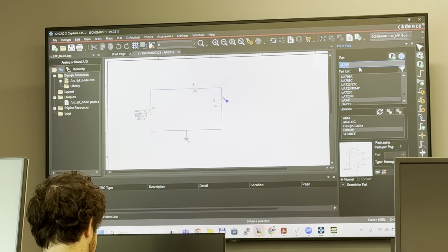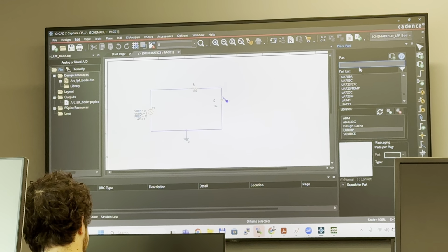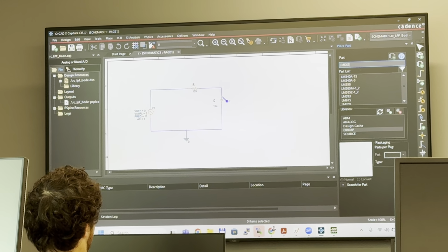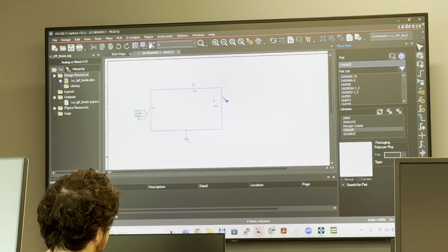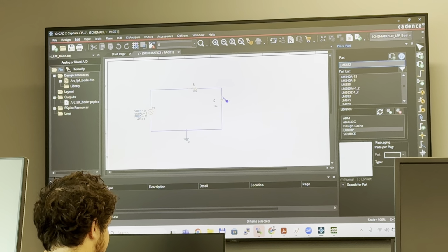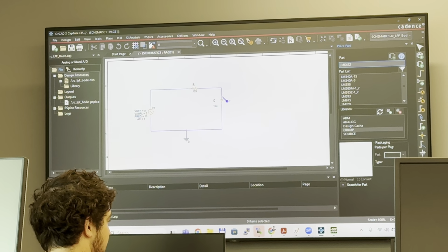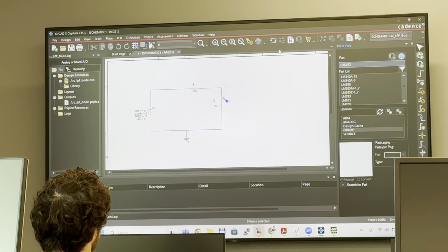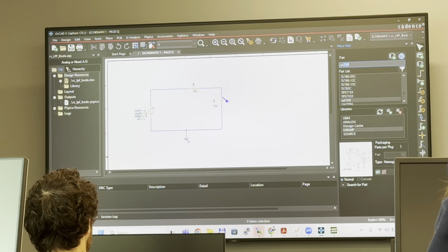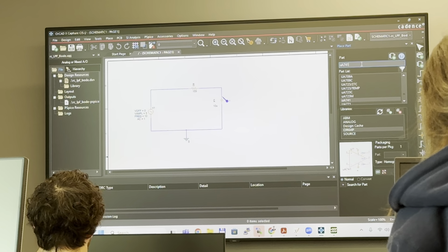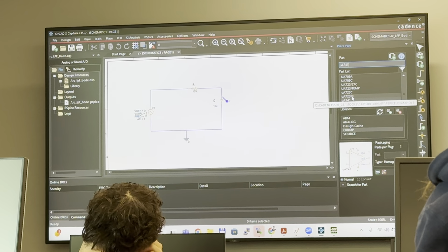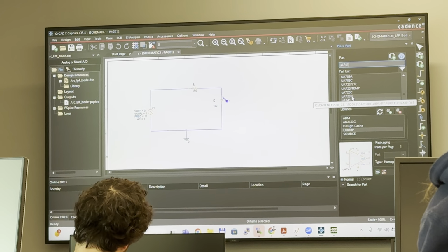But we do not have the model for the op-amp IC that you'll be using physically in the lab. It is the LM6482. No, we do not have this model, but we have this IC. This IC is an improved version of the 741. For simulation purposes, we will be using the mu A 741, which is the operational amplifier. But for practical implementation of the circuit, you'll be using the 6482. We have this in the laboratory.